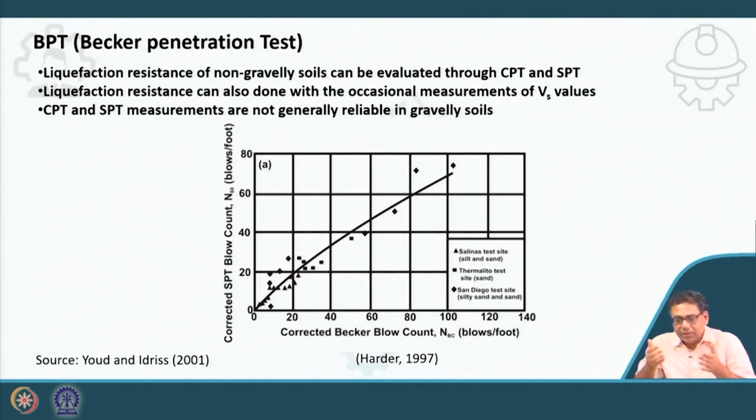That we know, and we have already discussed that. Liquefaction resistance can also be evaluated with the measurement of VS value. That has also been discussed. But CPT and SPT measurements are not generally reliable for gravelly soil.